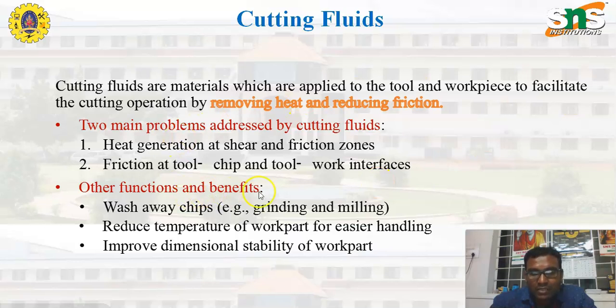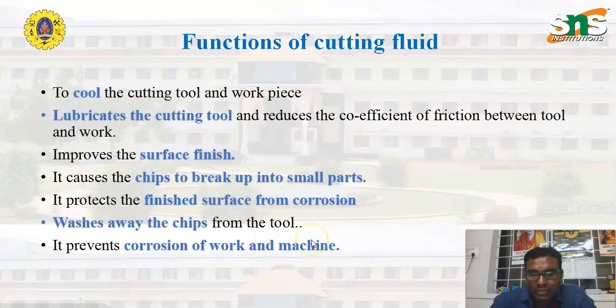The other functions and benefits of cutting fluids are: it washes away the chips during grinding or a major machining process, it reduces the temperature of the work part for easier handling, and it improves the dimensional stability of the work part.